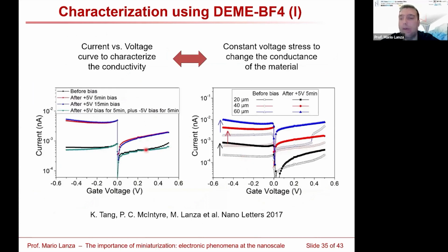After that, when we apply the voltage to the ionic liquid, we can observe the resistive switching. Here, initially the resistivity is high, then we switch it low, then it's back high. We analyze devices with different areas, and we observe there is area dependence, so there is no dominant filament.